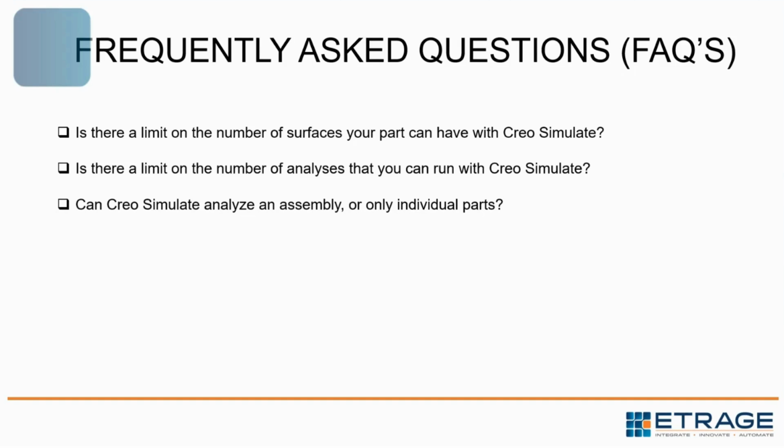Okay. Great question. Yes, there is a way to do that, built within Simulate as well, where you can define multiple parts together. You can define whether they should be fixed, like you said, like a weldment, or if you want to define it such that the two components are not connected together, but there is a weld at a certain location between both components,